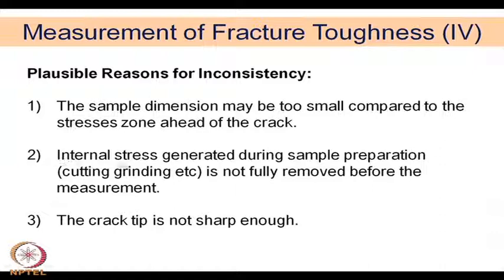The second important point to be noted is the internal stress generated during sample preparation, cutting, grinding, etc., is not fully removed before the measurement. As I have mentioned earlier, any ceramic material being brittle, there is always a tendency or a possibility of generating different kinds of internal stresses during sample preparation, cutting, because samples have to be cut and